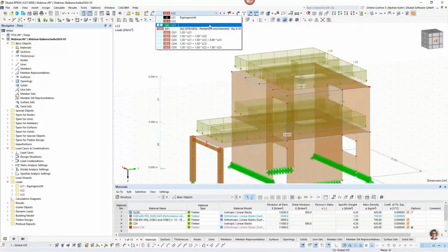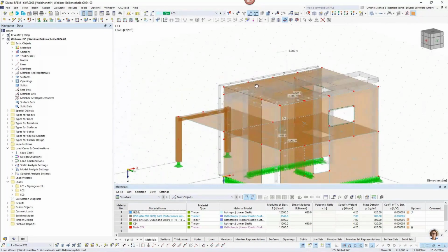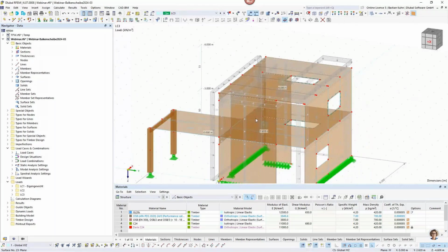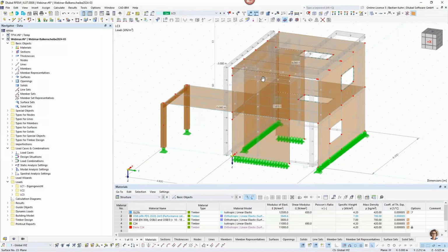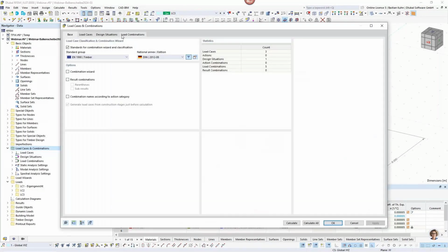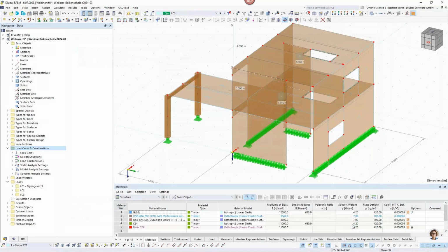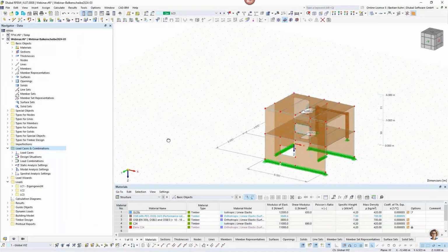And here in load case 3, I have generated the wind load blowing on the building from this side, from the front of it. So that's where I'm stiffening my structure, just for your information. And of course, I chose an automatic load combination and generated all the load combinations that we are using in here. Okay, so a lot of words I said.